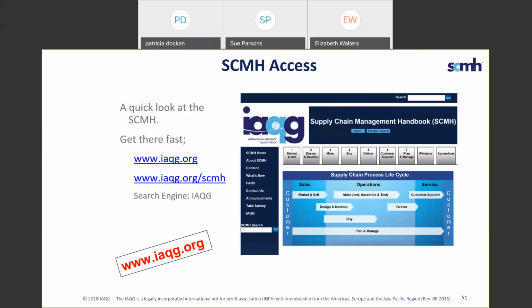There may be new key characteristics that need to go onto the control plan. Keep in mind that the control plan should always include the key characteristics or critical item characteristics that have been identified in either the DFMEA or the PFMEA.